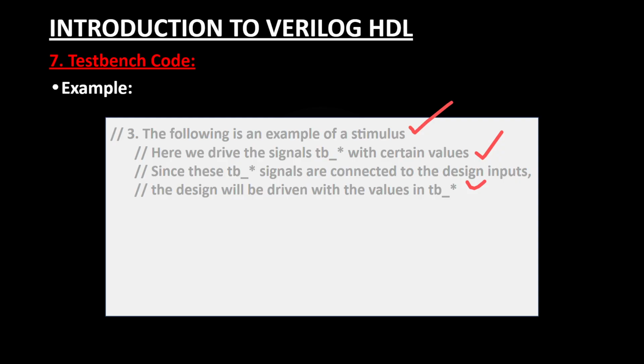We have connected the design inputs and the TB inputs, and the design output and TB output, right? So the TB test cases will be applied to the design inputs, and based on that functionality and those inputs, we will get some output, and we have to compare later. Next, the initial block. Initial is also a behavioral block which will only execute once. It will not execute infinite times like an always block, which is based on an event.